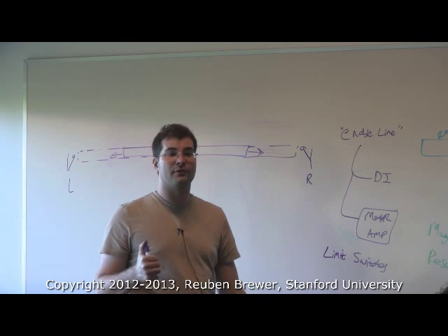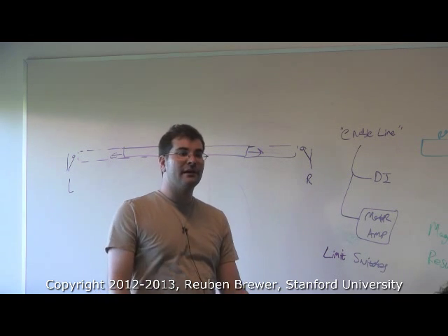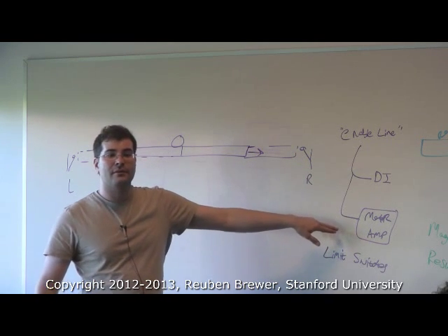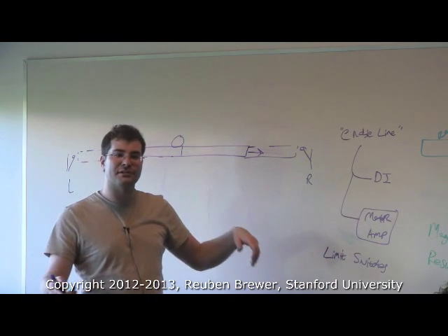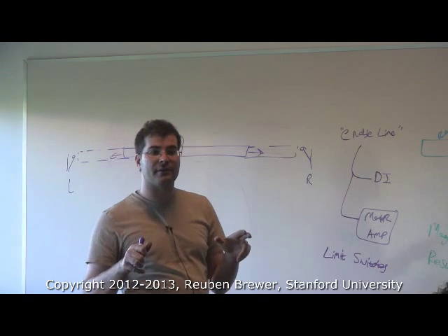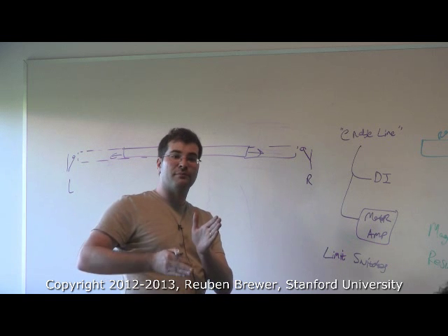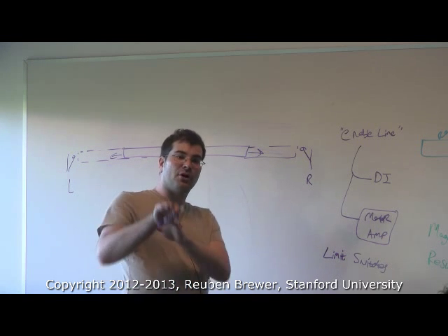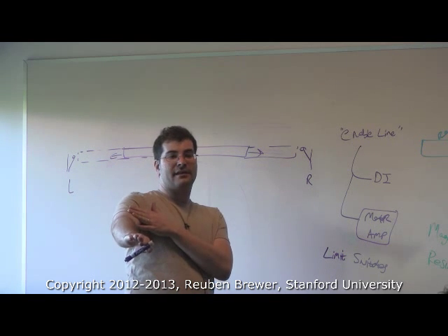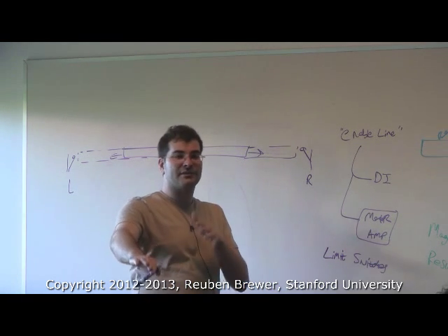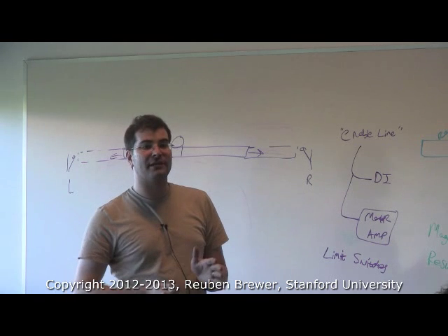If I'm debugging code and there's no patient nearby, I need a soft stop. So my enable line goes to the motor amp, but it doesn't kill power. 30 seconds later, I can unpress it and everything's good. The emergency button that cuts power directly from the wall socket is for when someone's arm is in there. I don't care what's going to happen to the robot. Someone's about to lose a hand, so I'm just going to literally sever power immediately.